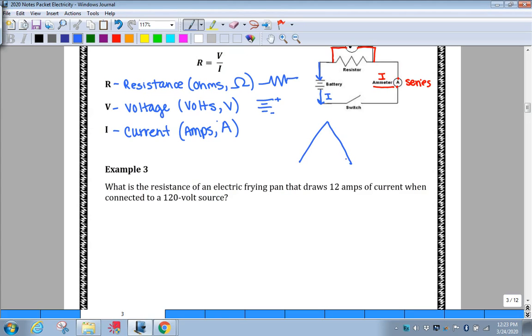All right, we're going to be using Ohm's law a few times today to calculate either resistance, current, or voltage. And if you have a hard time manipulating equations, this little triangle will probably help you. And the trick to it is cover whatever variable you're solving for. So if we are solving for, let's say, voltage, I would cover up voltage, right? Maybe I'll make that black so we can't see it. So I'm going to cover up voltage. And in order to get voltage, I'm going to multiply I times R. When they're next to each other, that's a multiplication. So to get voltage, I'm going to do V equals I times R.